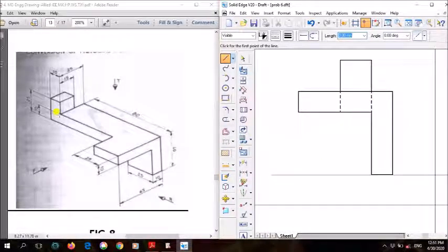Same way, another surface. If you forget this part and consider only this solid, this solid also has other edges here, right? And on that side there is another edge, so that edge is also not visible. Hence from here you join a line showing a dotted line. So this is one solid, and this is another solid, and this edge is not visible.